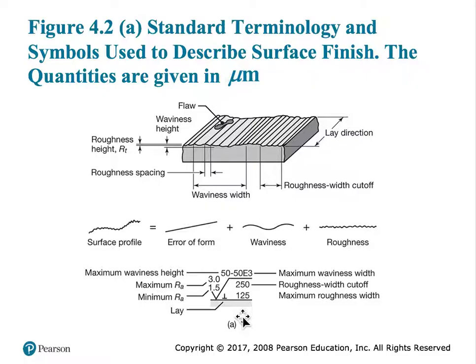Okay, and each of those has some kind of cutoff information depending upon the roughness. So if you have a very smooth surface, then that RMS value might be less. If you have a very rough surface, then you might see that it is up on one side and down on the other side. So on the average, that number could be pretty large. The larger it is, the rougher the surface is.